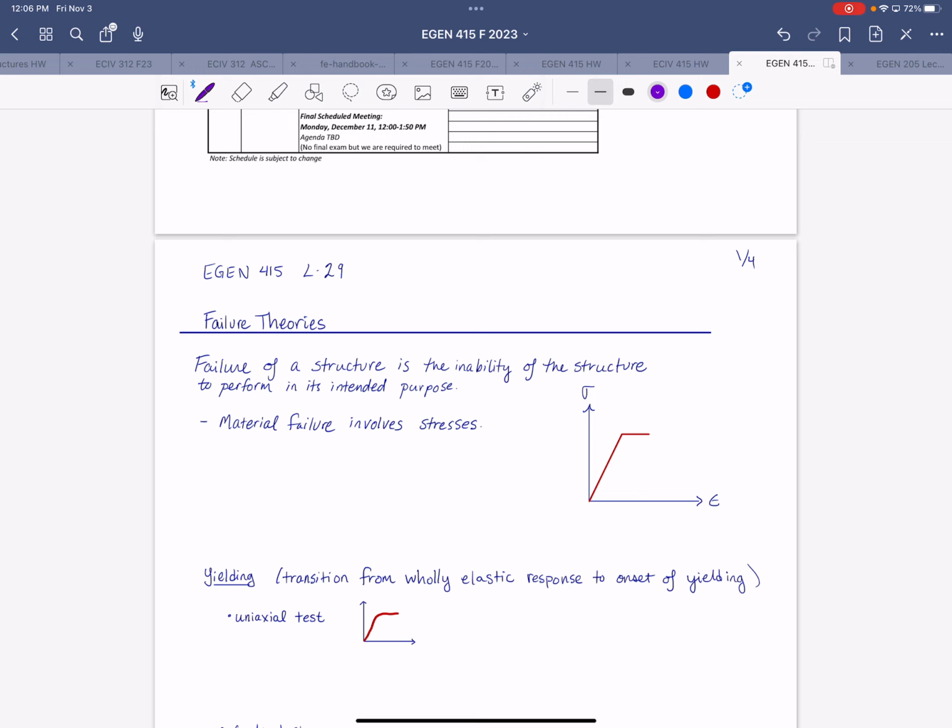Okay, so when you apply the dummy load, you would then have to go back and do Castigliano's, but setting the deflection at one side or the other equal to 0, to update your reaction forces. Or do you just look up in a table somewhere, reactions for a propped cantilever, which I don't know.